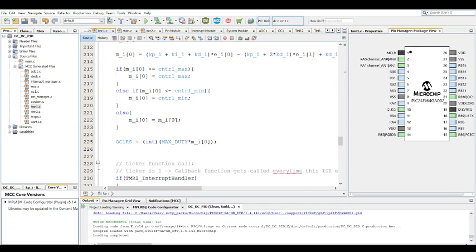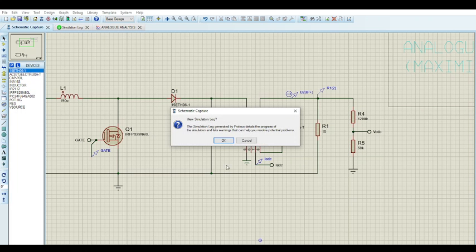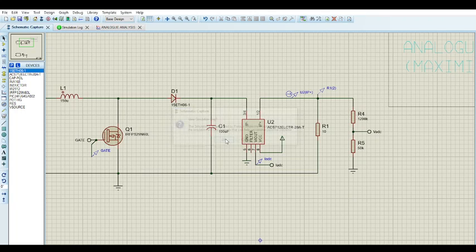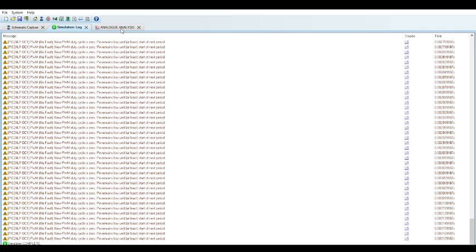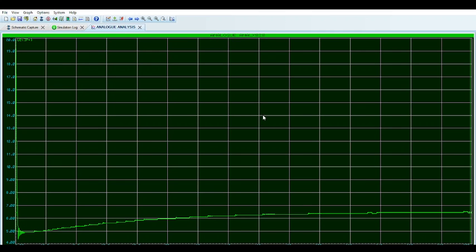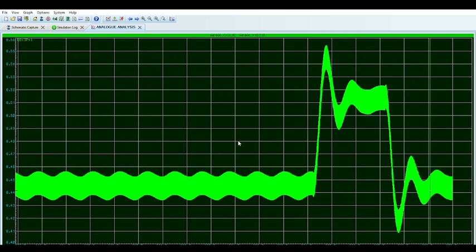But the hardware, you touch it, you don't solder something properly. Your sensors are not soldered on properly, so basically your PWM just goes to 100% all the time, or 80% in this case. So you kind of have to be careful with the hardware. You massage everything, make sure everything is operating properly, and as you can see, it gets there faster, and it's not unstable.